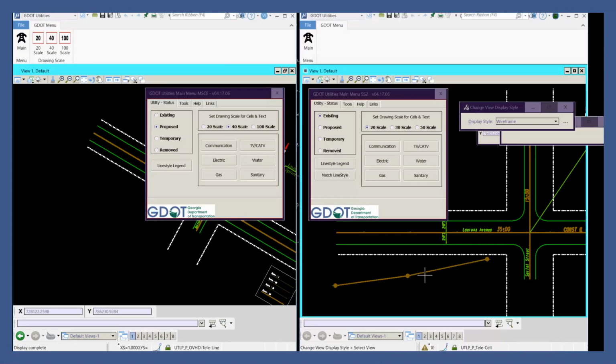Since MicroStation Connect Edition has the dual workspace configuration to accommodate both Select Series 2 as well as MicroStation Connect Edition projects, we had the option to choose the SS2 workspace when we launched MicroStation Connect Edition. And had we done so, we would have the 20, 30, and 50 scale options for MicroStation main menu SS2.